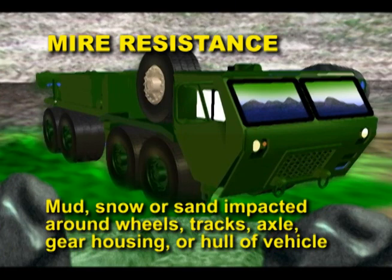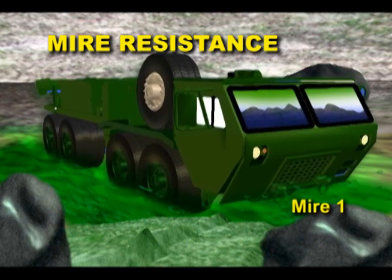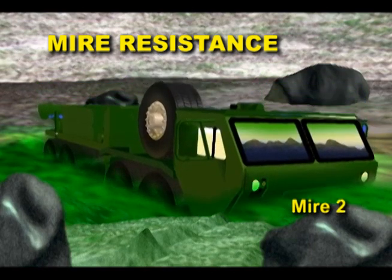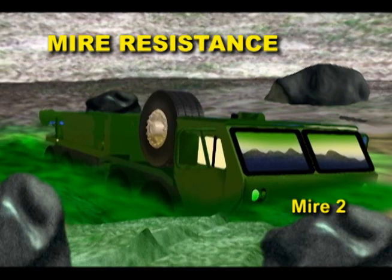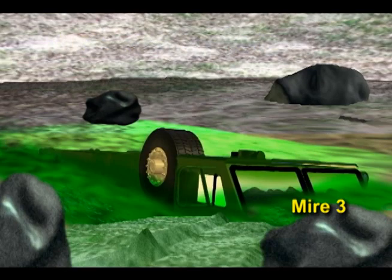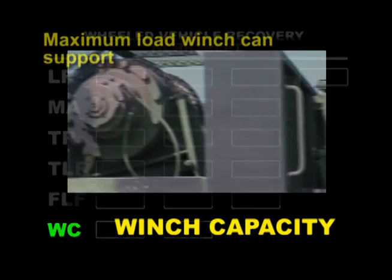Mire resistance is created when mud, snow, or sand becomes impacted around the wheels, tracks, axle, gear housing, or hull of the vehicle. There are 3 levels of mire resistance. Mire factor 1 is mired to the center of the hub or less. Mire 2 is mired between the hub and fender. And mire 3 is mired over the fender to the cab or turret level. Winch capacity is the maximum load your winch can support.